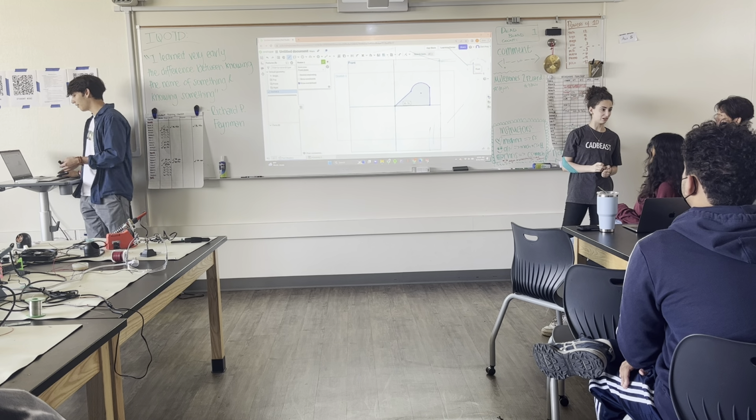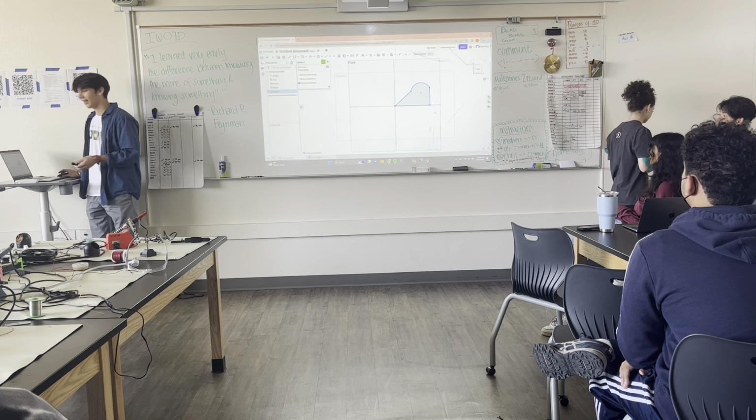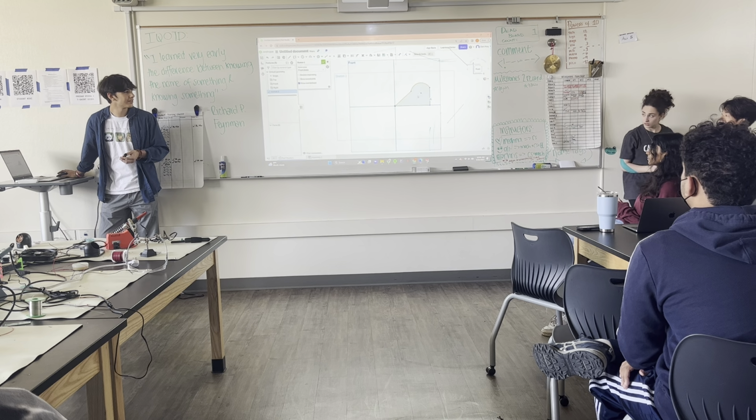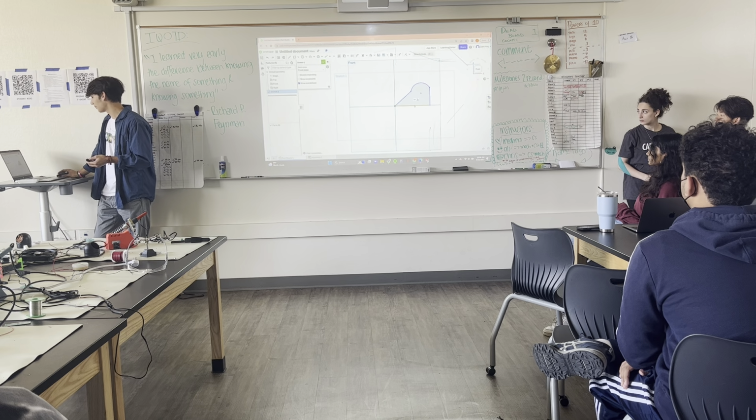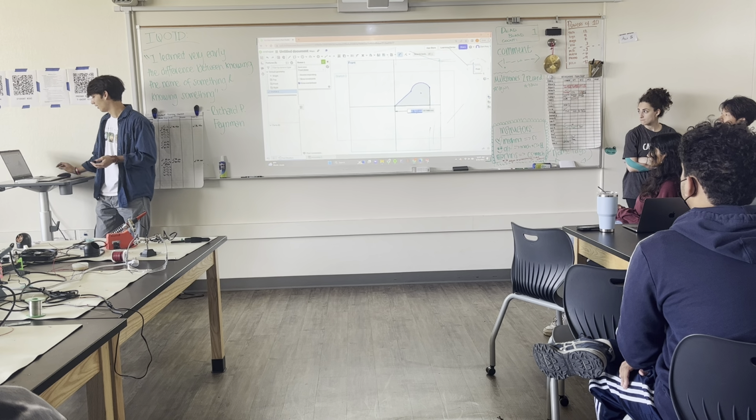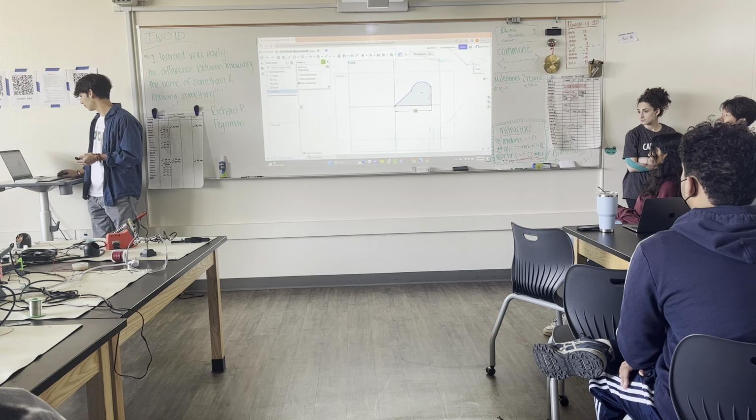Okay, so here I've made a closed figure. You can tell this is a closed figure because it's slightly shaded in. But you can see that all of my lines are blue, except this bottom one. The vertex is still blue, which just means it's not fully defined. So what you do is you take your Smart Define tool here.